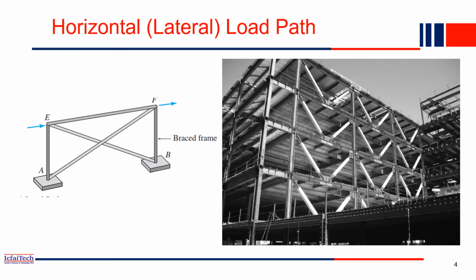So whatever we have discussed in the previous slide was basically a vertical load, but your structure may be experiencing a horizontal load also, like the wind load we discussed in the last slide. So wind load is basically a horizontal load. Because of horizontal load, you also need to provide some bracings. If your structure is situated in a heavy wind area, then you have to provide extra precaution for the wind as well. So these bracings are normally provided to take care of the horizontal force.